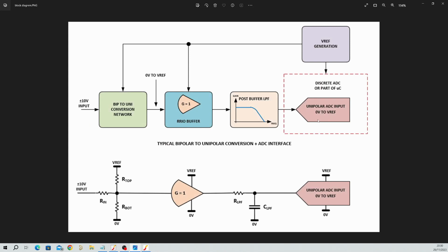And like I say, if it's a discrete ADC, a standard reference will more than power this, and if it's an ADC like in a microcontroller, there normally is a cal high and cal low reference input for the ADC section. So you would pair that section, and then it's all ratiometric at that point.